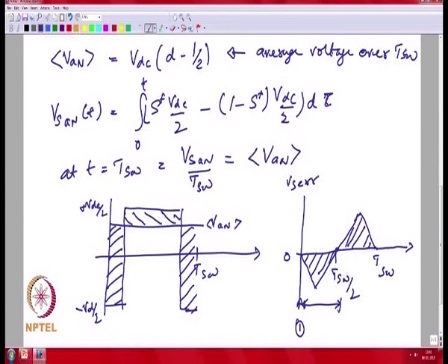This is often used in a power converter along with the model of your output filter. When people model the inverter for digital control, they might model the inverter as a zero order hold. If you look at the phase delay of a zero order hold that is being updated at a rate of TSW, the delay is actually TSW by 2.